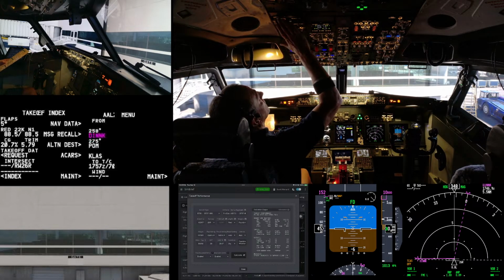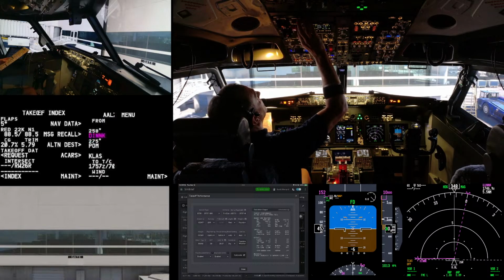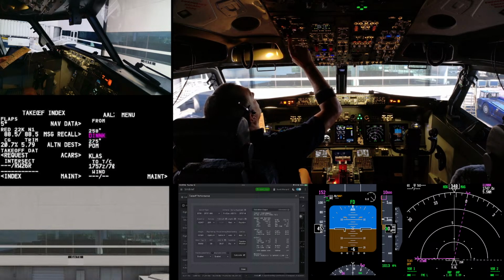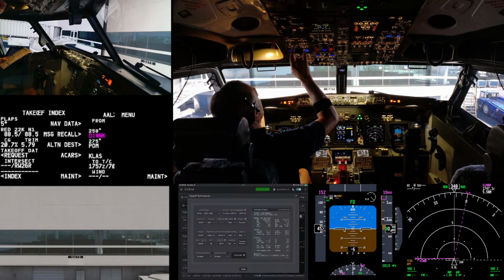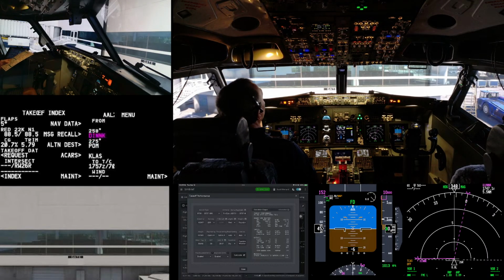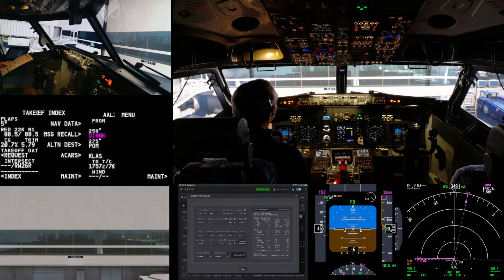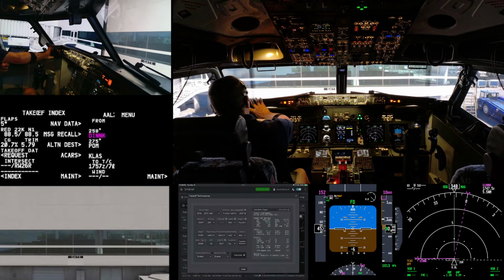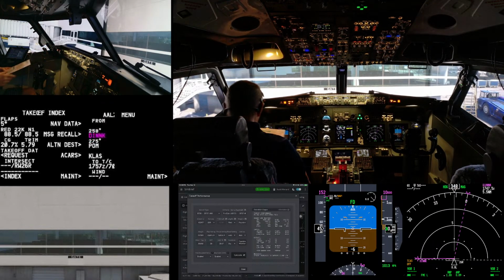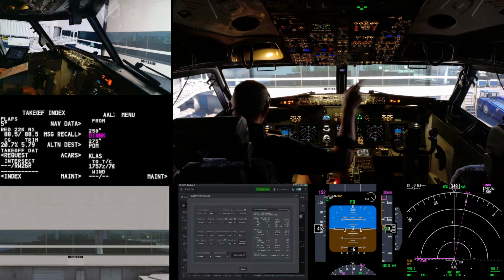PSEU is checked and flight controls are guarded, standbys confirmed, hydraulics good, spoilers are armed and guarded, yaw damper is on, check, navigation is normal, and displays are auto and normal, fuel cross feed valve operable, and we're going to put number 1 forward tank on for now for start the APU. Let's go ahead and start that. Started the APU, and I made sure the bleed is off.